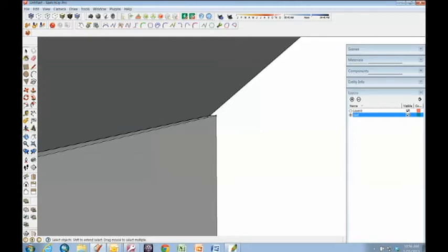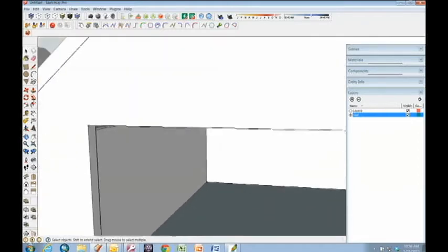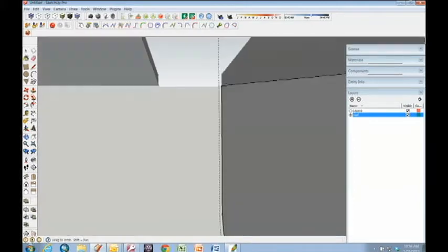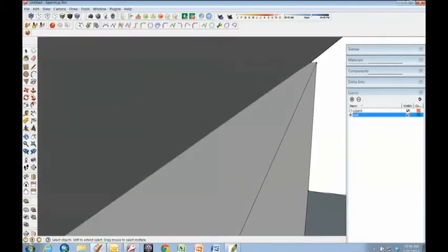One thing that you can address later is where these walls don't meet the roof. You can lower the whole roof down until it intersects, or you can bring those walls up. But if you're going to set these walls at a height that is real, you're going to want to leave it like this and probably drag the whole roof structure down until it closes that gap. But for now, we're just going to play around with this thing.